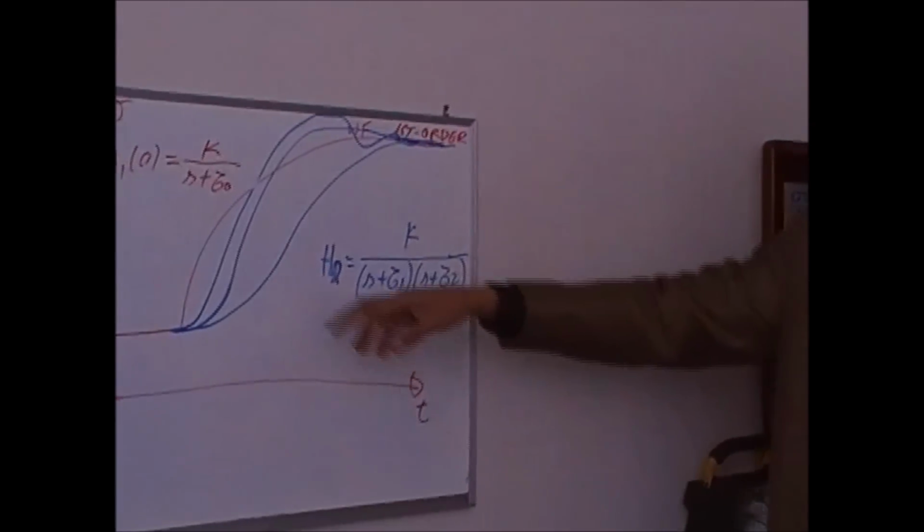So we saw today what identification is. Identification is taking a physical system and deriving a model for it. The model can be first order, second order, or even higher order. There are different ways to do identification. We presented here one that is convenient for a first order system.